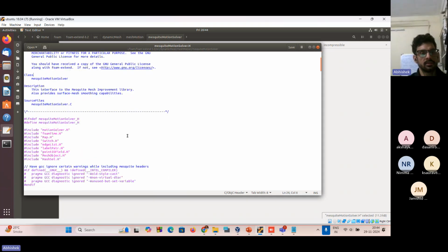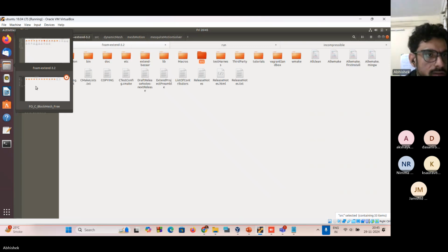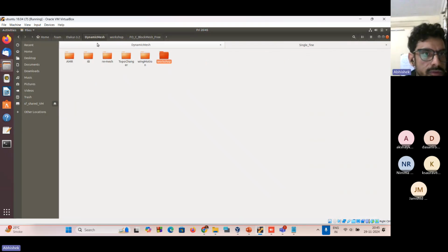All right. So what I did, I took that wing case, the mesh morphing wing case tutorial that we had. I changed that for mesh morphing in a single cylinder, then changed that to a tutorial with tetrahedral mesh in cylinders, and then we have the topoChanger heavy mesh. So what I finally did is I changed that case for the remeshing part.